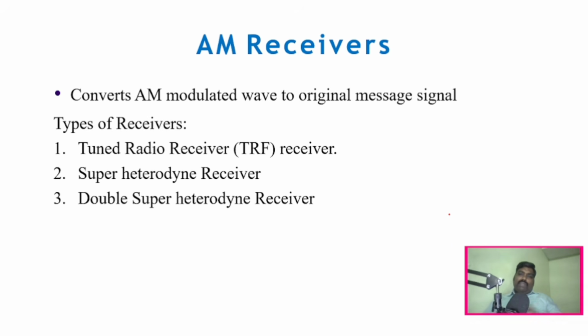We have already seen the functions of the receiver, and you have to understand here that in any RF communication, the signal processing has to be done at lower frequencies, whereas the signal transmission has to be done at the higher frequency, to minimize the cost, because processing a high frequency signal increases the cost.